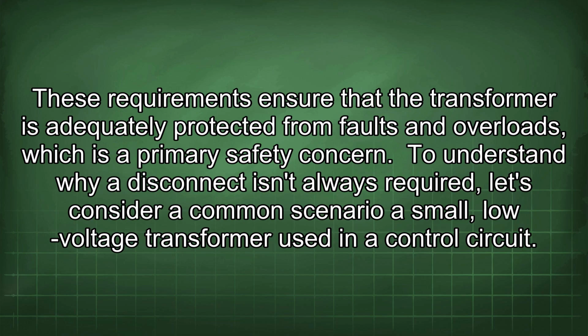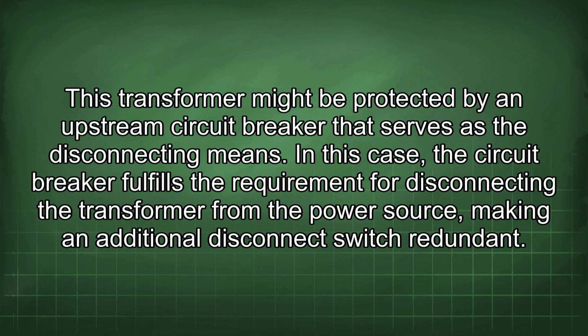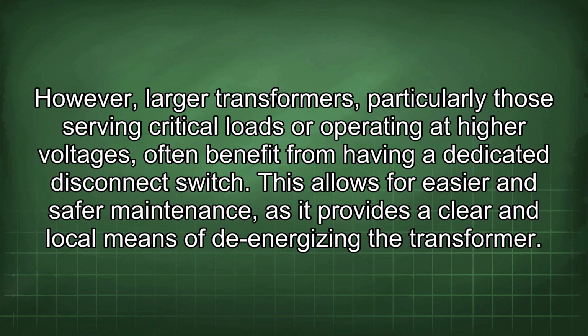To understand why a disconnect isn't always required, let's consider a common scenario: a small low-voltage transformer used in a control circuit. This transformer might be protected by an upstream circuit breaker that serves as the disconnecting means. In this case, the circuit breaker fulfills the requirement for disconnecting the transformer from the power source, making an additional disconnect switch redundant.